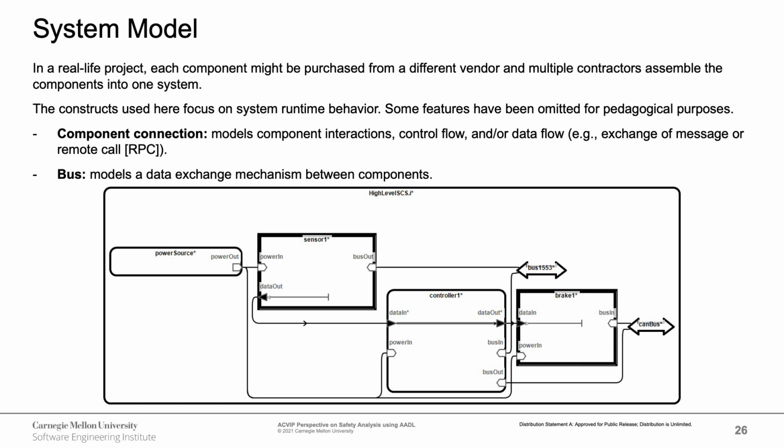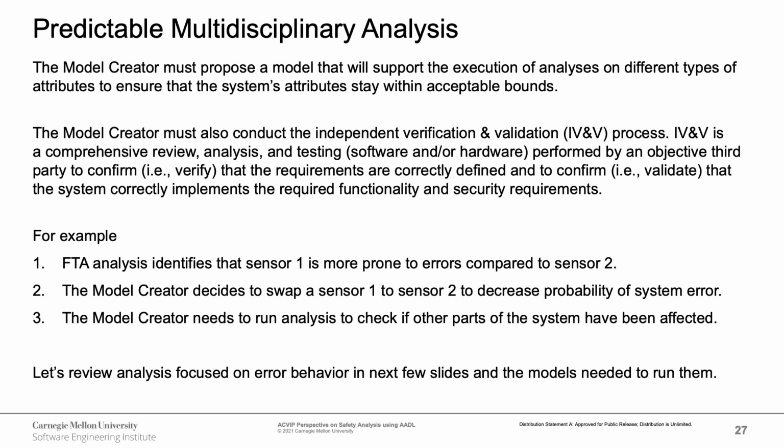It virtually integrates multiple components that you wouldn't see working together normally before implementation. AADL analysis can help identify errors in device communication that otherwise would be missed. Getting back into ACVIP methodology mindset, we would want to get more familiar with the cycle of changing a model and running analysis until all of the requirements are fulfilled and no issues are identified by AADL analysis. As we get later in project development, things will be more precise, but predictable analysis provides early guidance for decision-making.